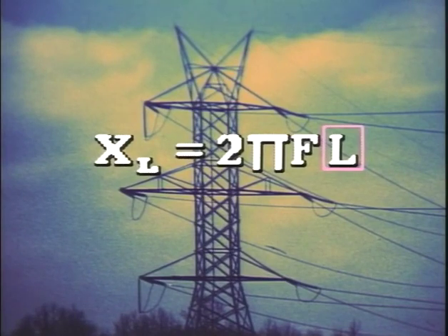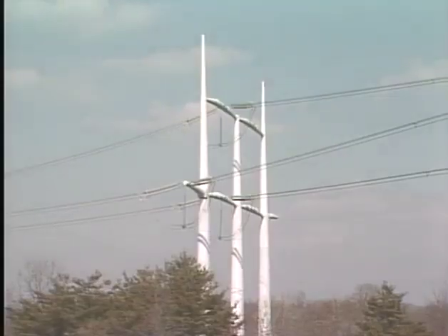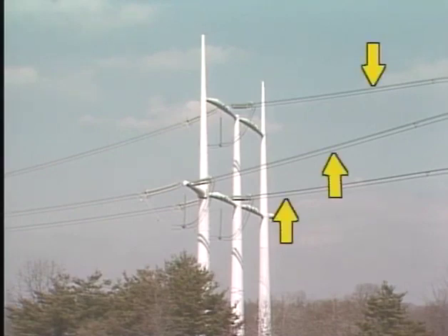Since inductive reactance can contribute to power loss, controlling the inductive reactance in a transmission line can help minimize power loss. One factor a designer can use to control inductance in a transmission line is spacing. In a transmission system, spacing refers to the physical relationship of phases to each other and to the relationship between conductors. Transmission lines must be designed to prevent phases from touching one another, resulting in phase-to-phase faults.